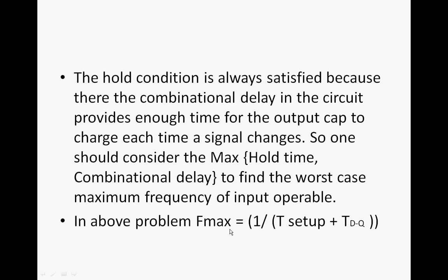So in this case, the maximum frequency of operation would be 1 by T setup plus D to Q propagation delay. This is what we have to consider. We have to consider the maximum of hold time and combinational delay to find out the worst case maximum frequency.